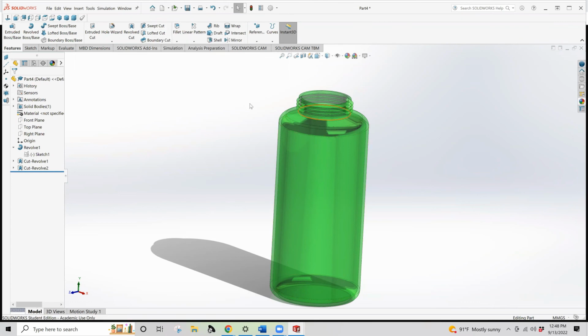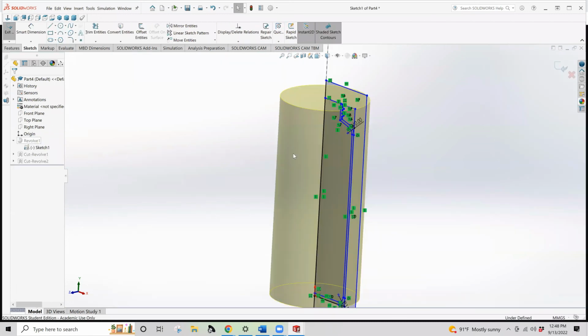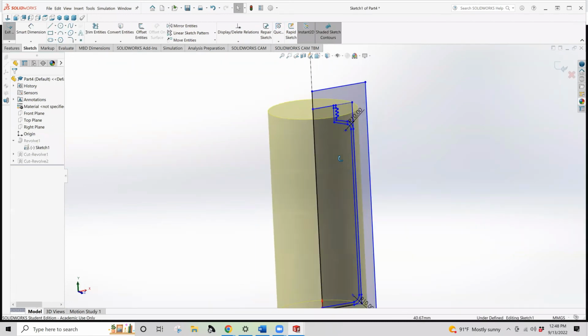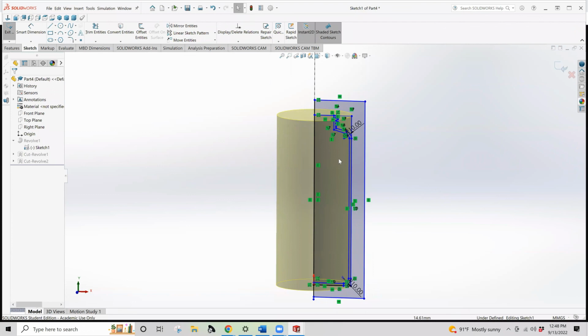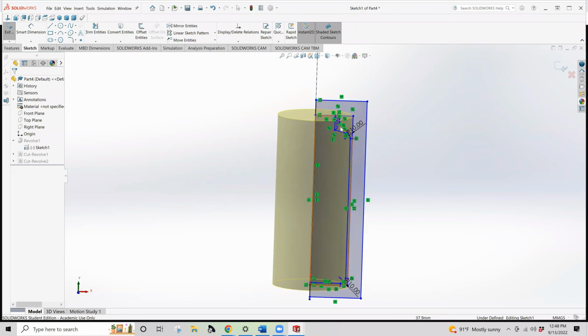But we're going to do a lot of focus on this part, the detailed drawing, because this is where most of your work goes into. You want to capture absolutely as much of the 3D geometry as you can by thinking carefully about the symmetry of the object. So what's the axis of symmetry, and how do I leverage the power of that to get me the most features for a single operation like a revolve?